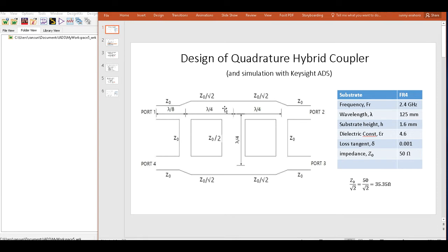We have a combination: there is a 3 dB hybrid coupler 1 and a 3 dB hybrid coupler 2. The combination of these two 90 degree couplers will give us 180 degrees at the end. These are connected in cascade, so this results in a 0 dB coupler, where an input signal will cross over diagonally to the opposite output.